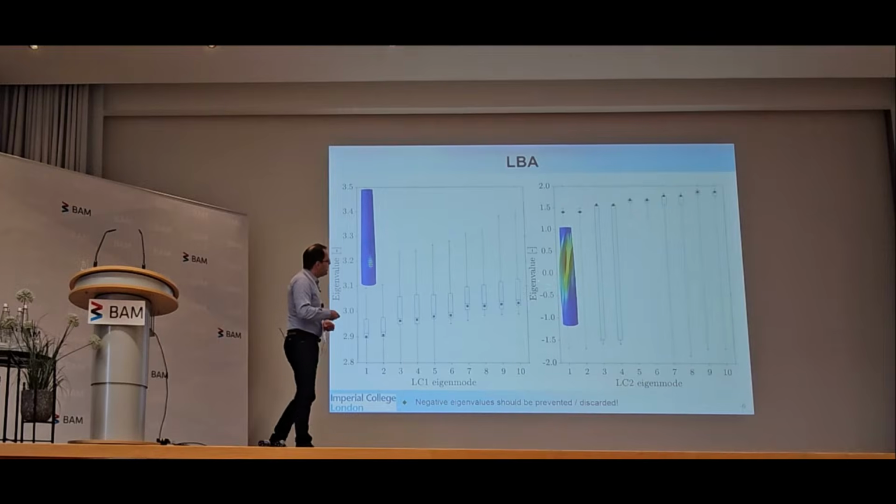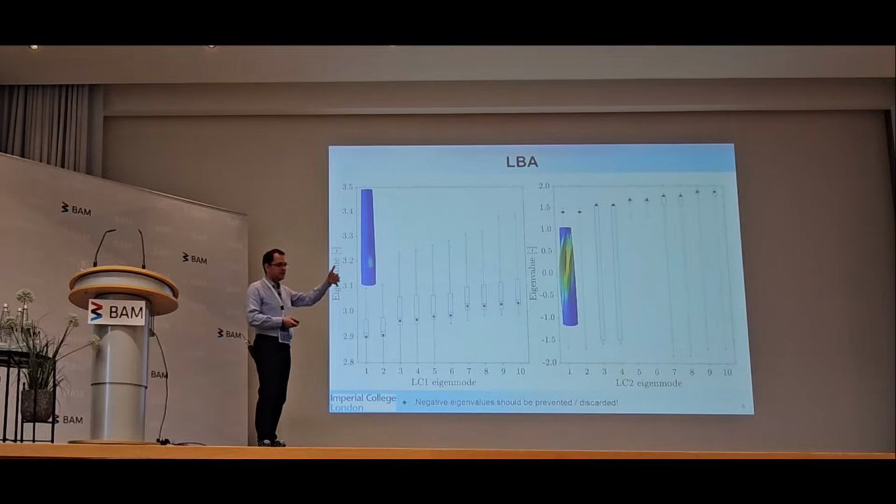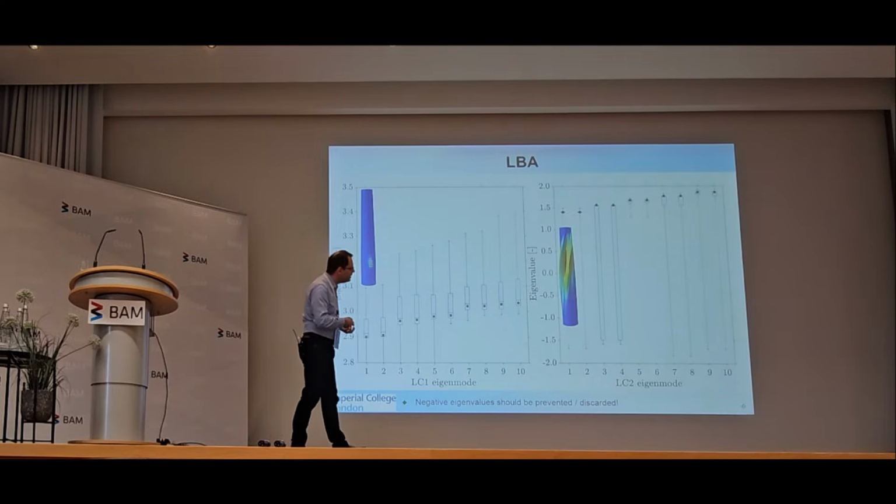So far so good. Now, LC2, the torsional one, presented a few challenges because the torque dominates the system so much that if you were to reverse the loads, the torque acting the other way is as critical as the torque acting one way, because this kind of shear buckling can act in any axis, really.